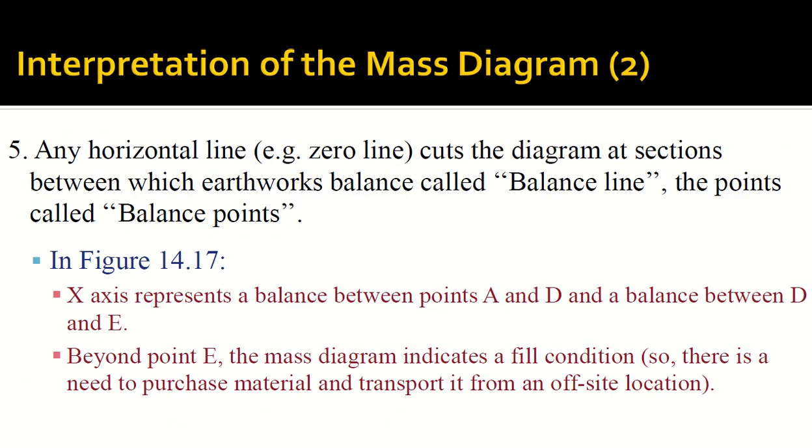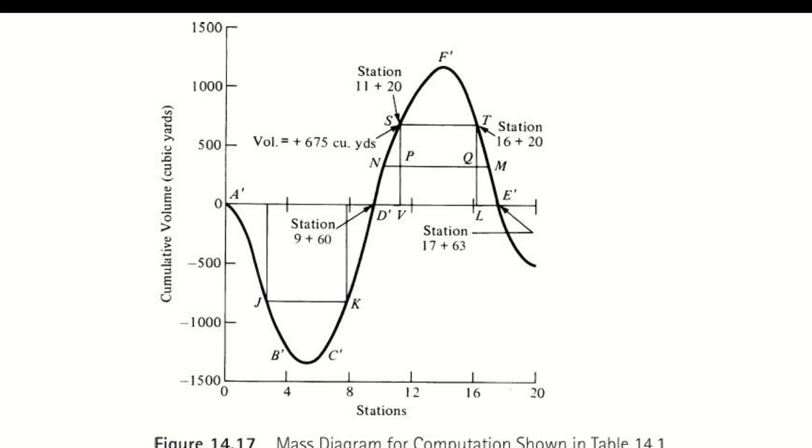Okay, we will not do the overhaul calculations now, but just to explain, you have to come to the graph. You will put a scale or something here, and you will see where the distance of 500 feet is, where the 2 ends are at the same level. Okay, so for example, I put a value here, and I see, can I go to the other end of the graph at 500 feet? Okay, so if I'm at this point and I try to go 500 feet forward, I will not reach the other end of the graph, right? So this level is not okay. So I have to go down. Okay, so this is how you do trial and error on the graph.